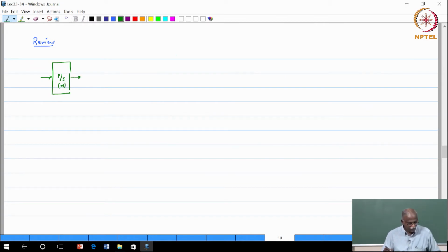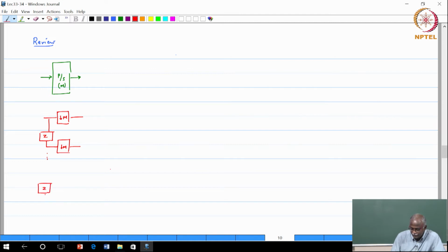Okay. Now, do you remember how this was done, parallel to serial conversion? Do you recall? Again, basically it was a downsampler by m, that was the top branch, and then we passed it through an advance operator, right, because if x0 is on the first branch, we want x of 1 on the other branch, which means that it must have passed through an advance operator, downsample by a factor of m, dot dot dot, last advance operator, and then you passed it through a downsample by a factor of m.